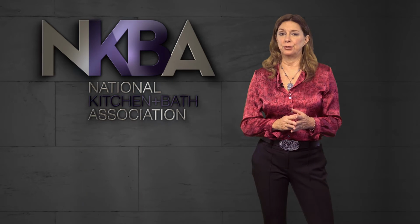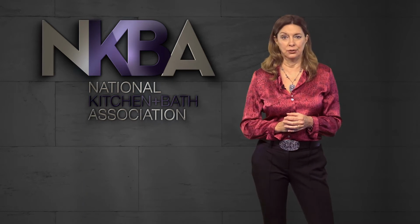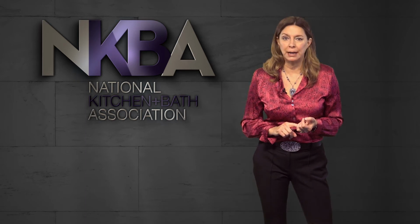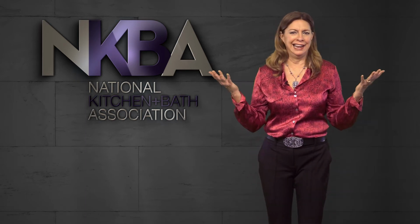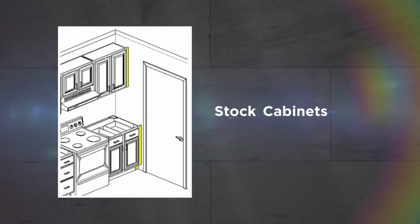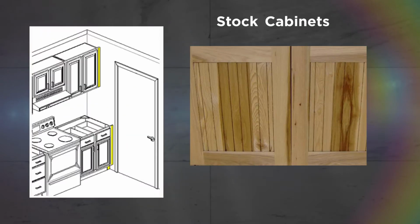So here's the deal with cabinetry. It falls into 4 broad categories: stock, semi-custom, custom, and millwork cabinetry. Now you may be thinking, hey, they all look the same. What's the difference? Check it out. These are stock cabinets and they're built in incremental sizes, typically 5 to 10 centimeters or 3 inches. Now not all walls in every home or office are divisible by 3. So what happens if you have 2 inches of empty space left on a wall? What do you do? The answer is you use something called a filler.